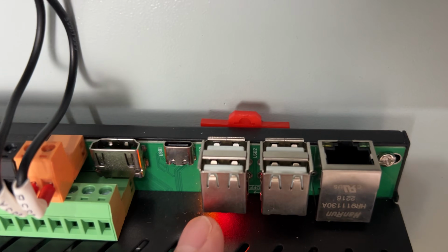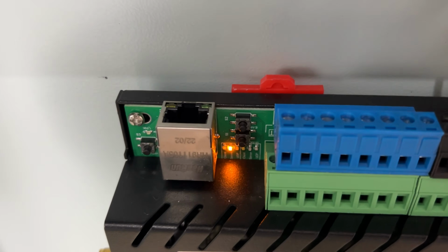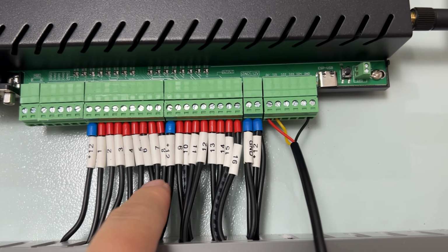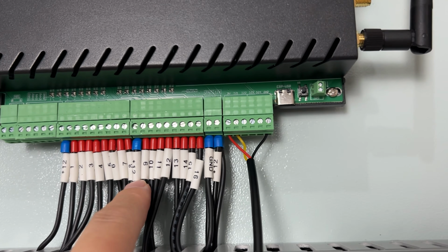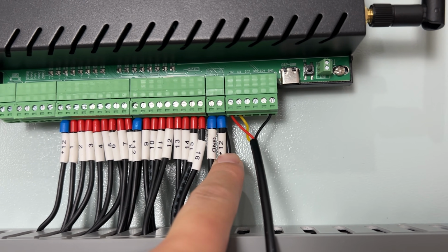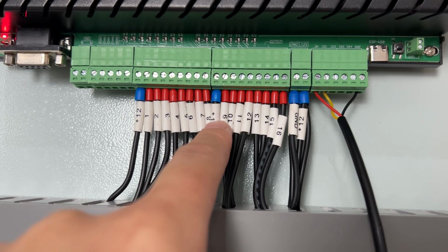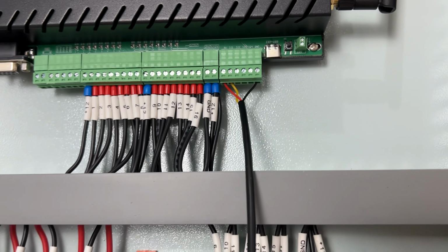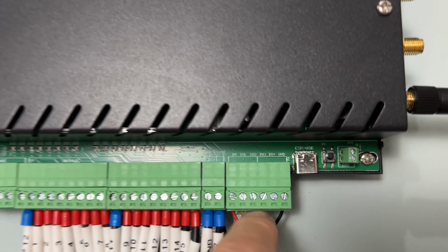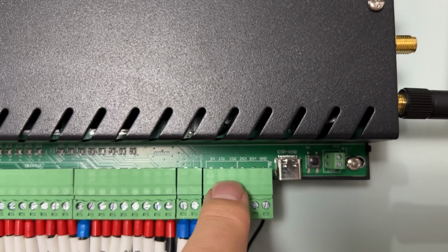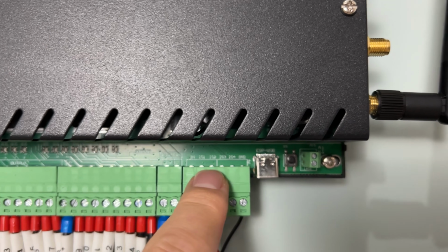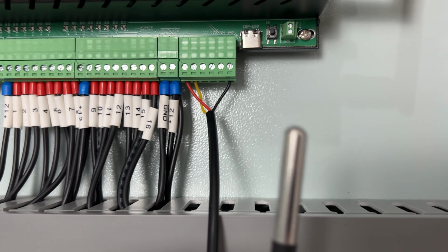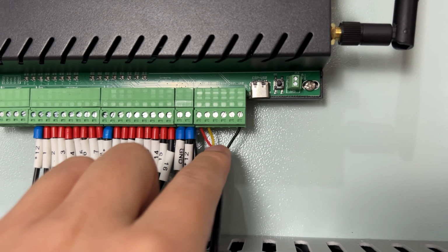And this is a terminal. This terminal. And this is output. If you want 24 volt output, you just connect here a power supply with 24 volt, and these two lines, this 12 volt, also replace with a 24 volt power supply. And the temperature sensor, and this is free GPIOs for ESP32, so you can connect the DS18B20 temperature sensor, or you can connect the DHT11, DHT22. That is a temperature and humidity sensor together.